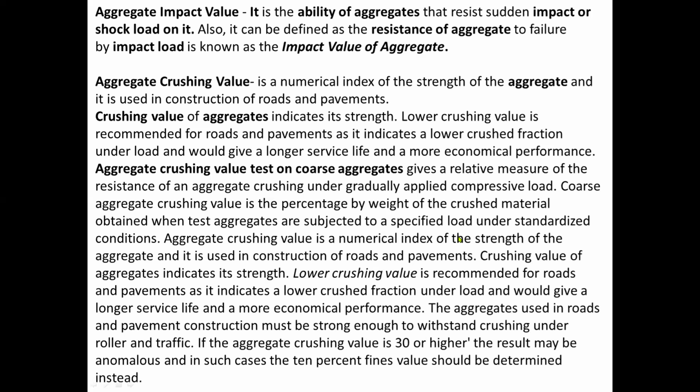The aggregates used in roads and pavement construction must be strong enough to withstand crushing under roller and traffic. If the aggregate crushing value is 30 or higher, the result may be anomalous, and in such cases the 10% fines value should be determined instead.